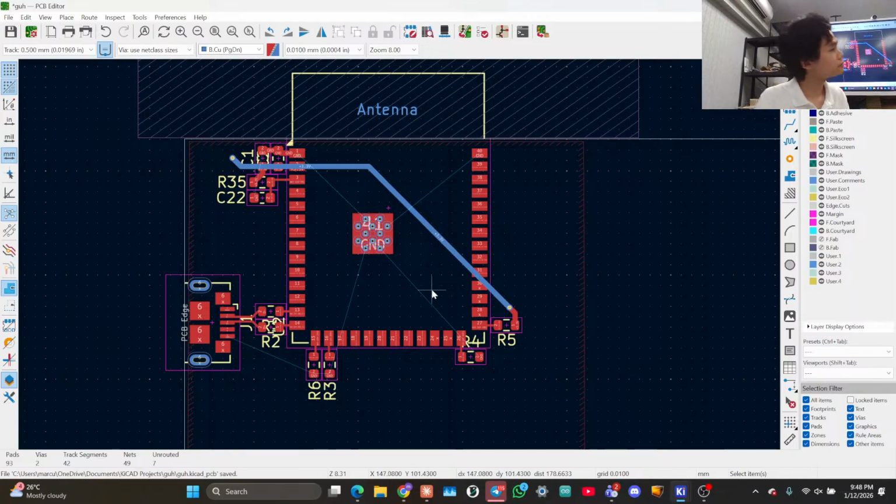When we do this, do we have to be careful of impedance? I mean, for power, usually you're okay. You need a low impedance connection from the decoupling capacitor to the IC. The IC being like the ESP or literally anything. IC means integrated circuit, so a chip basically. So that needs a decoupling capacitor, right? Anything that draws power needs a decoupling capacitor. But other than that, you just make it low impedance and you're fine.